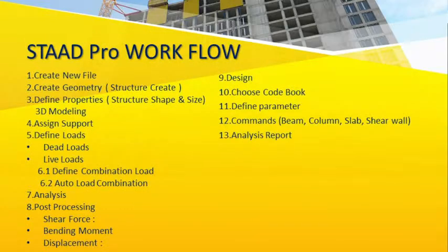And how will the workflow be in STAAD Pro? In STAAD Pro the workflow is: first we should create a new file. After that we will create the geometry, like how many floors we require, how many columns, how many beams, how many slabs we require. So we will create the geometry. Then we will define the properties, like what the structure's shape should be, what type of shape it is, what size, and what type of material. We will assign the properties.